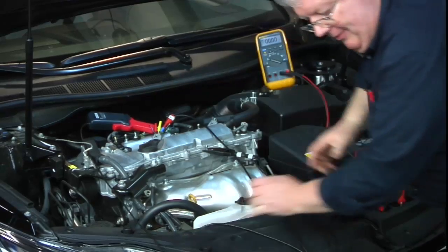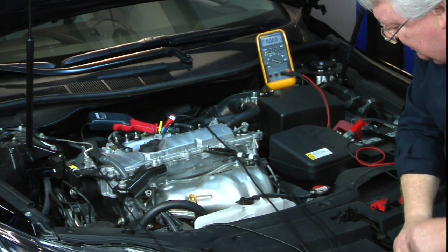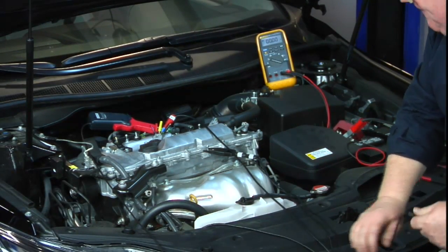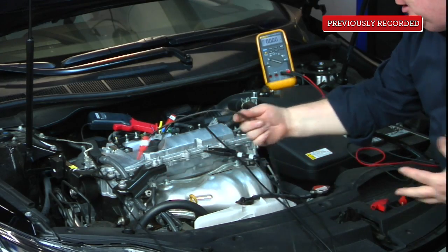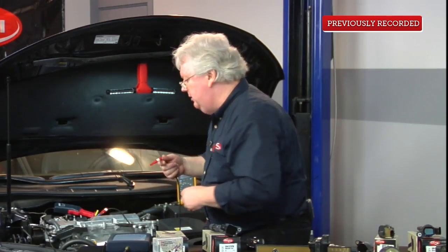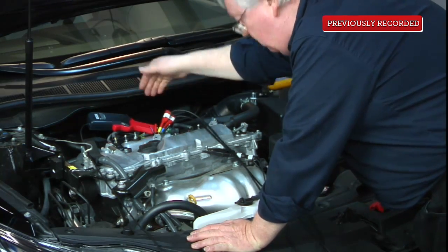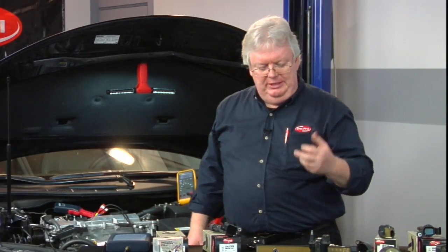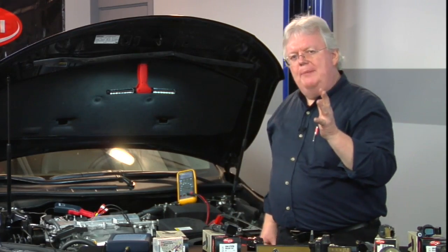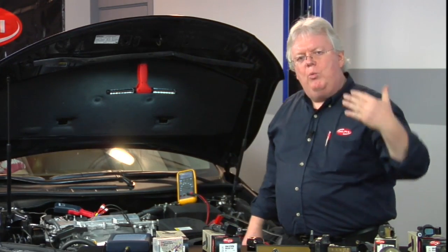Trigger. And then channel B, that's going to be the feedback. So we can see the feedback of all coils working, doing their job, reporting into the PCM. And for number 2, our cylinder in question, we can see what's going on with the trigger from the PCM. So now let's go ahead and start it up and see what we have for current ramping of how the